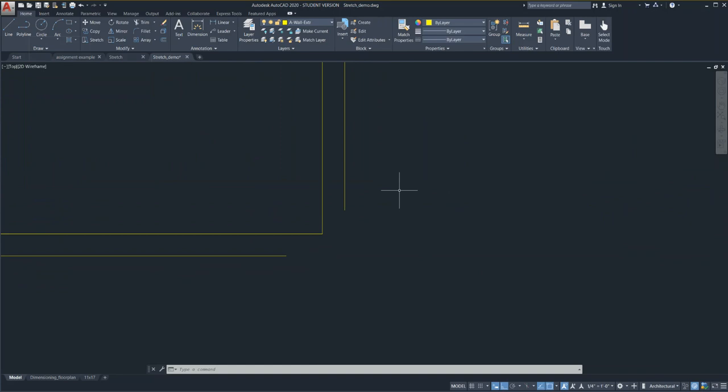What will define if a fillet rounds a corner or makes it squared off is the radius that you specify. A 0 radius will create a squared off corner, and then something like a 1-inch radius will create a 1-inch rounded corner, okay? Things that you will use a rounded corner for, let's talk about that.